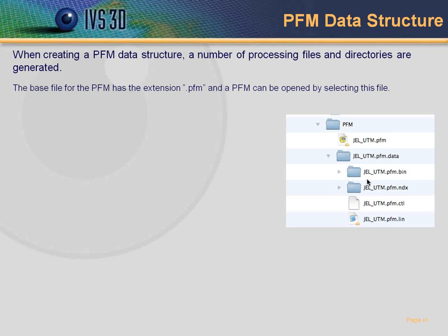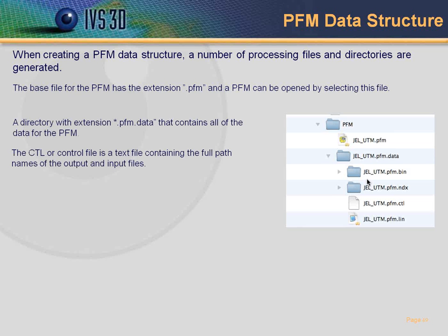And you should note that when you load a PFM into Fledermaus, import PFM, you can actually save an SD file. So now you have, say, GELUTM.SD, but what's important to realize is that SD file is really just a pointer to the larger PFM file.